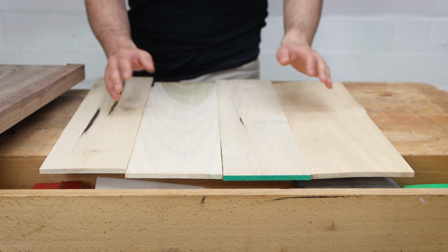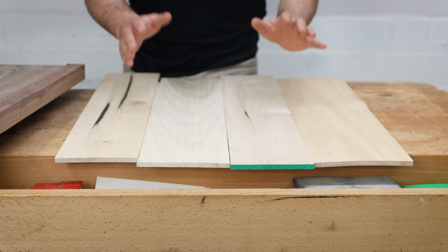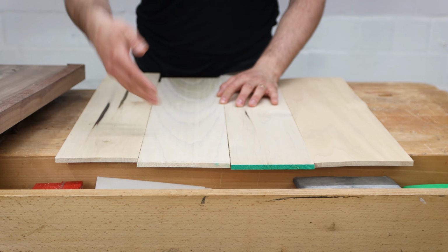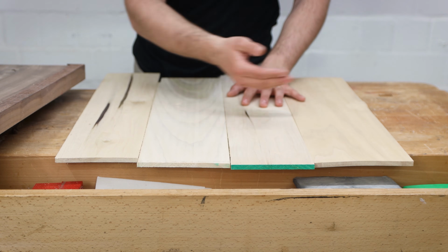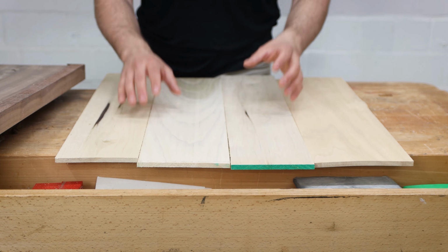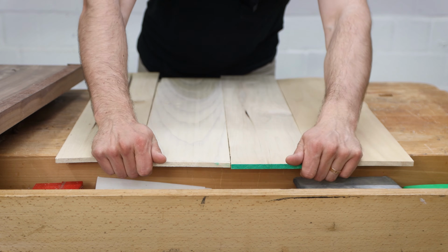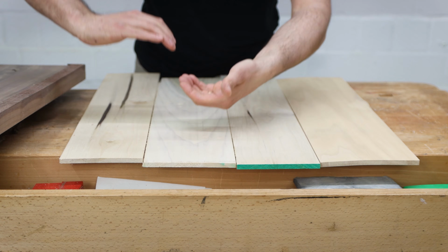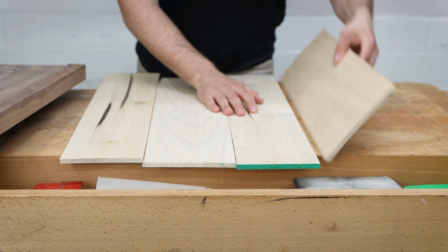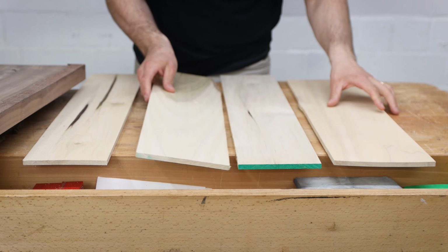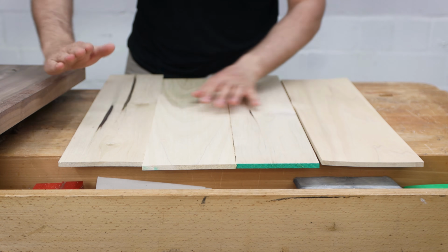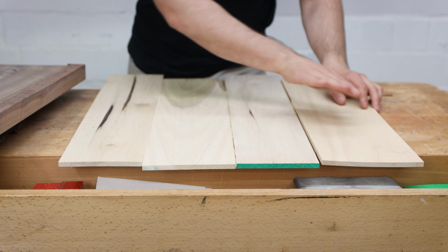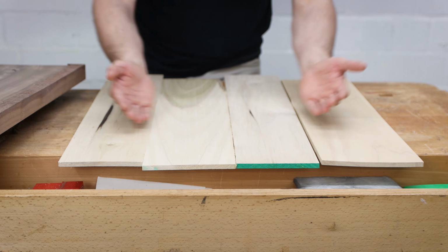Let's continue. A second construction method is for panel glue-ups. When you glue up a panel and align all the growth rings in the same direction, which means the growth rings are going this way, this way, this way, and this way, your panel will cup significantly in one direction. It means it will cup down and actually create something like this, pretty big. But if you alter the direction, say like this, and also here like this, your panel is going to stay flatter. It will create a little top like here, and then a bottom here, a top here, a bottom here. So it's just this wavy little pattern instead of one giant cup.